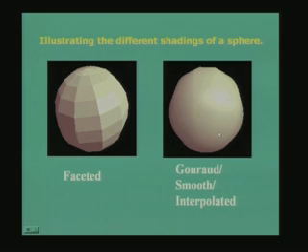And you have to visualize that we have not taken a finer sweep representation of a sphere and tried to do shading using faceted shading. No, that can be done, but that is not done here. Same wireframe representation, but Gouraud, or smooth, interpolated shading gives such a fine picture, at least of the smoothing, if not for this surface, of the intensity variations.